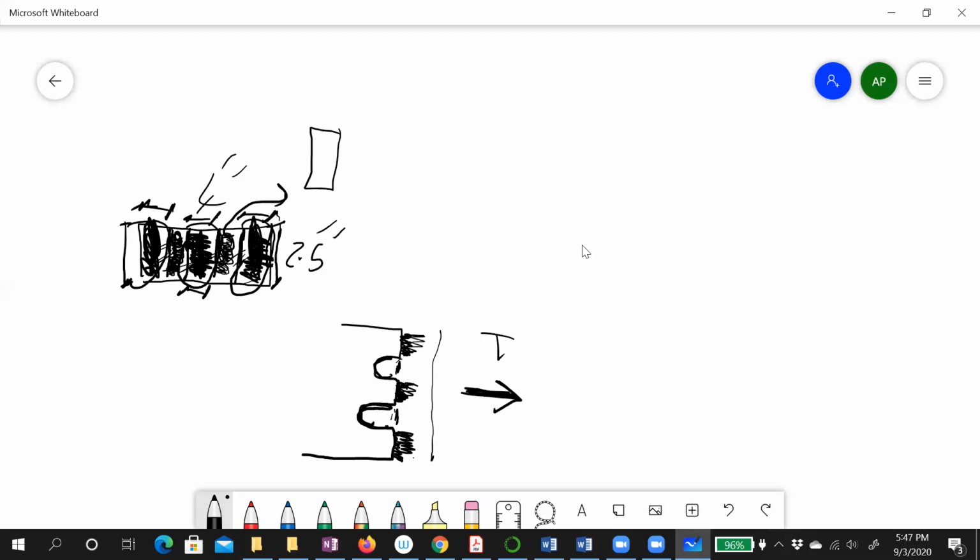The reason we want to find the maximum, the critical one, right? Because if you go to other sections, for example, this dimension is less than that one, which means more area for the wood to contribute to the stress, so less stress. Okay, that makes a lot of sense now. Yeah. We pick the critical part.